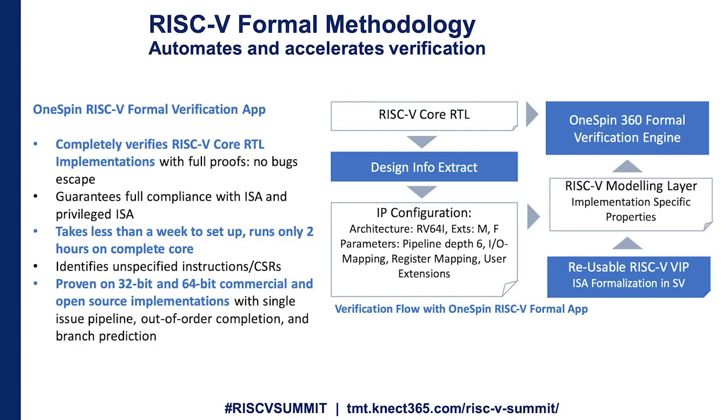In order to help the user speed up, we enabled some functionality to extract some microarchitecture details directly from the RTL. Let's say you have the Rocket core. The assertions come in a checker, and they need to be bound to the core. When the Rocket core generates the code, it uses random naming, so in order to do this binding you would need to find out what the register names are. This is also easy to extract from the RTL, along with some other microarchitecture details.